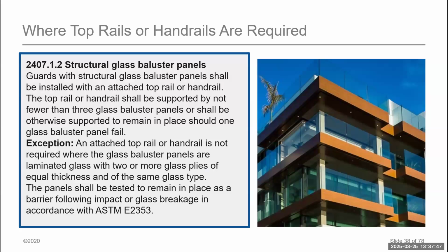The other thing that we also have to be concerned about is we have that element that fastens to the building at the substrate, which is the base shoe, the base clamp, or the adapter. Then we have the glass that goes into those elements. Then we also, by code, commonly need a top cap on that system. And that top cap provides a few benefits, and we'll talk about that later in the presentation.